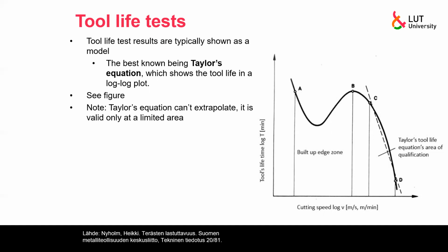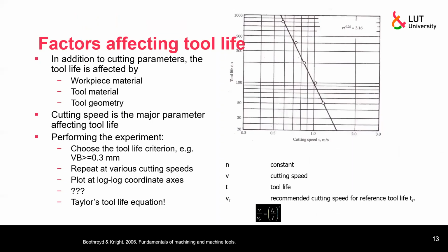But then when we're on the proper cutting parameters, then roughly in that area we can estimate the wear with the previous equation, which has a simplified form of something like that. It was a straight line on a log plot, so cutting speeds and tool life should form a straight line. So we'll do a couple of measurements and fit that line there.